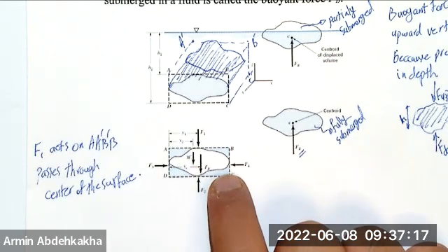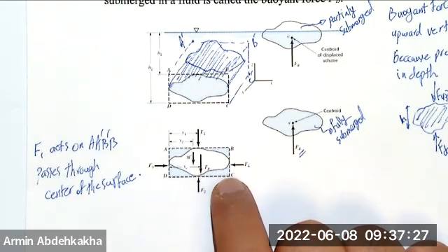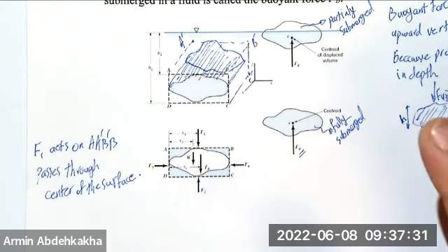Because it's easier for us to write the force balance for the fluid. We are saying that everything is based on the fluid. We have a control volume. We don't care how much of this is filled. We put the boundary of the control volume outside of the object, so everything, if there is an object, is inside the control volume. Then let's write the boundaries and the forces.